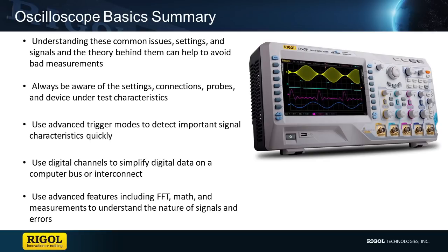Then on the scope side, right, we talked about a lot of things that can get in your way: settings on the coupling, the bandwidth, sampling, probe loading. All sorts of issues can cause you trouble if you're not used to making measurements, or if the person who was in the lab before you left the instrument in a different state than you're used to, right?